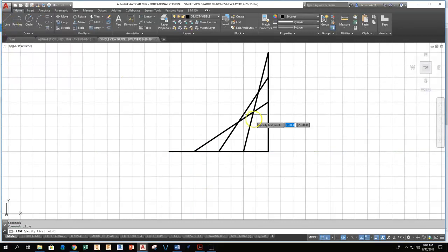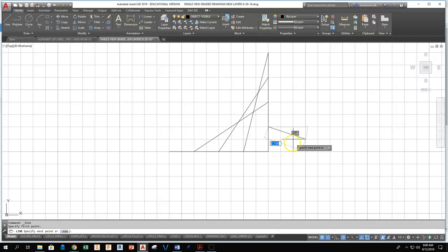And notice that I actually sit there for a moment. If you run too quickly, whoop, see how I clicked up here, and this is what I want you to see. My OSnap is turned on down here. Let me turn off my line weight so you can see this a little better. My OSnap is turned on, and my endpoint OSnap is showing up. When I come up 1 inch from my last line and sit there, it has the tendency to jump back to my OSnap.